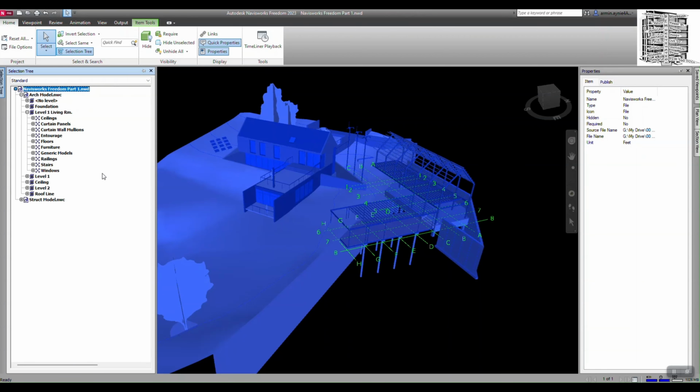I think these are really good pointers to use during your coordination, and I want to go over the Project tab at the end real quick. If you do the drop down, we have Appearances and Transform. You might move one object, and if you hit Transform, it brings the object back to the original location. This links the objects together, or any links from different sources. And with Appearances, if you change the color and transparency for one object, when you hit Reset Appearances, it takes everything back to the original or native color.